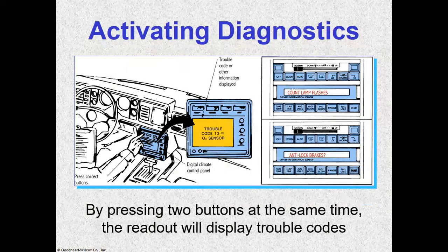This is why I was saying with the OBD1 system, it varies across the board. Just imagine somebody driving a vehicle you never worked on before and they want it scanned. If you don't have the manual, you probably would have to tell the person you can't scan it, if you don't have a scan tool and you try to retrieve the code manually. With the OBD2 system, you see how it just makes life easier for us as technicians.